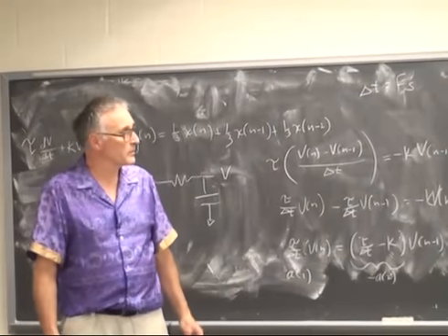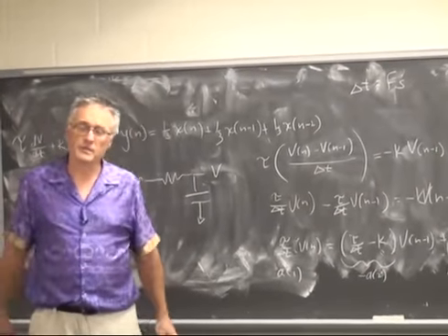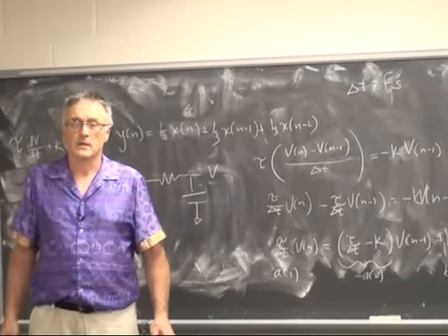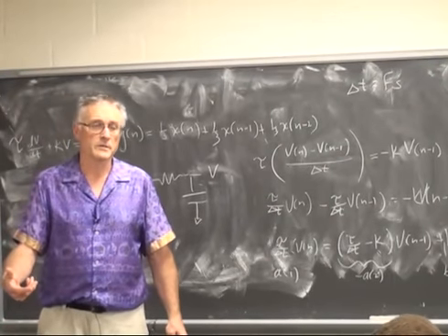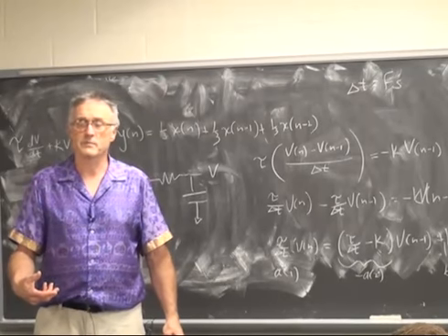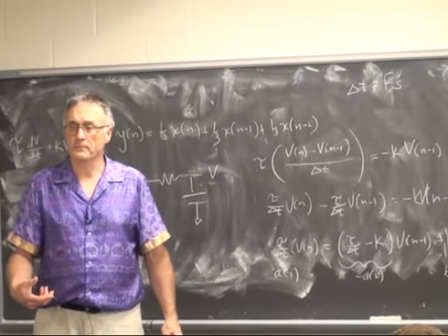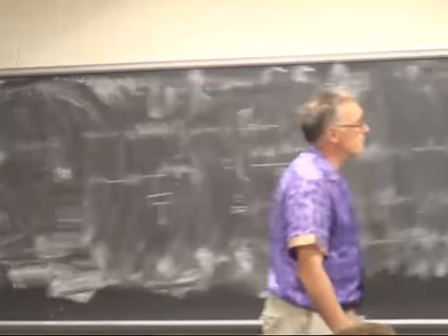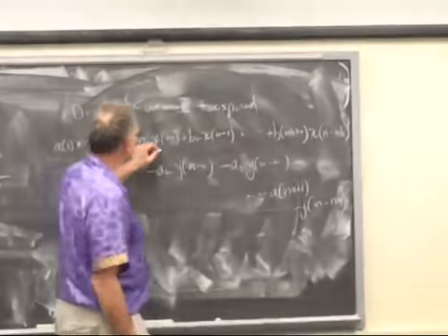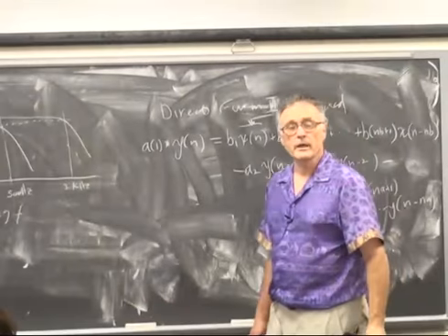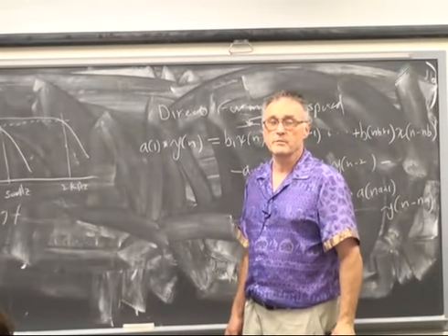Separate CPUs. So the software you write is going to be a straightforward piece of numerical analysis that does a bunch of adds and multiplies, adds them together, and spits them back out of the audio codec. So each new input is going to come from the audio codec as a 2's complement 16-bit number.